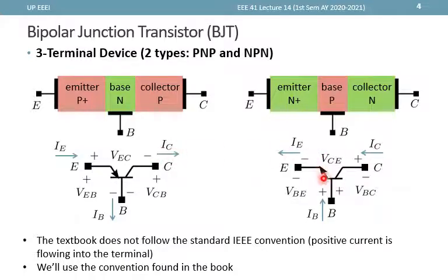And in this symbol, the arrow is leftwards, and so IC must be leftwards. So for some practice, consider this symbol here. Now, since the arrow is outward of the device, then this must be an NPN transistor. The terminal with the arrow is the emitter. The one at the middle is the base, where the other terminal is the collector.